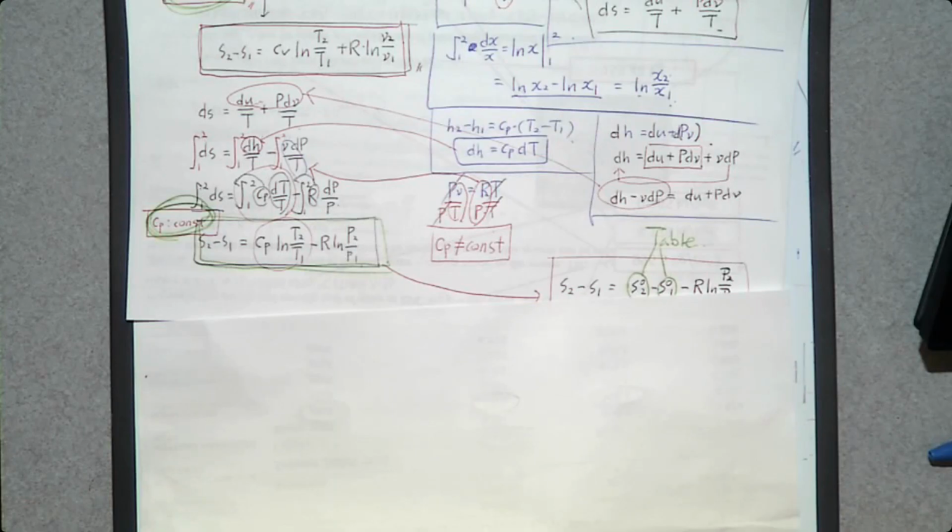If entropy does not change, that means the process is reversible, because no useless energy has been created. So one of the things we want to know while studying entropy is what process has entropy S remaining constant. That is called an isentropic process.